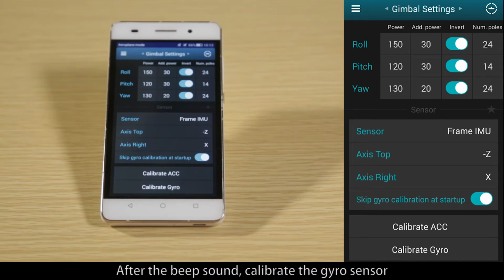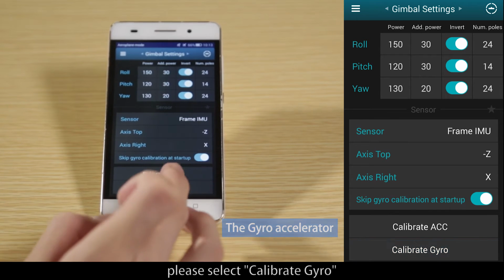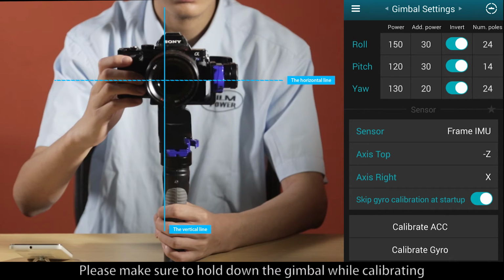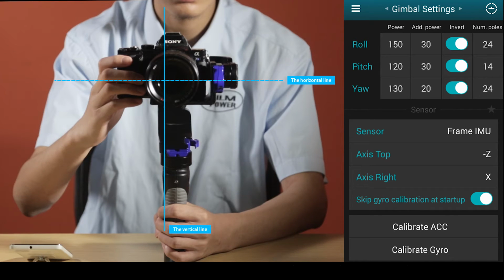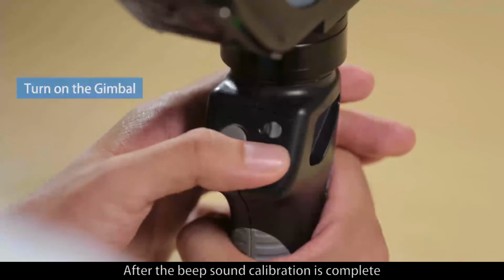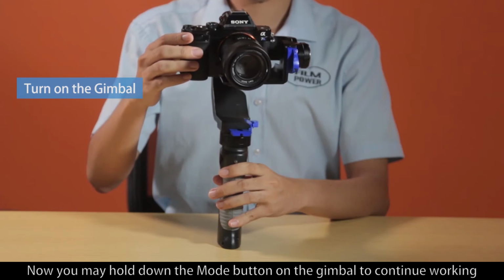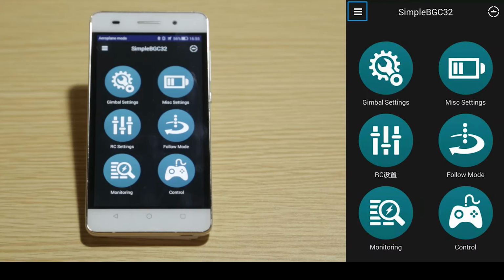After the beep sound, calibrate the gyro sensor. Please select Calibrate Gyro. After the alert tone, gimbal starts calibrating. Please make sure to hold down the gimbal while calibrating. After the beep sound, calibration is complete. Now you may hold down the mode button on the gimbal to continue working.